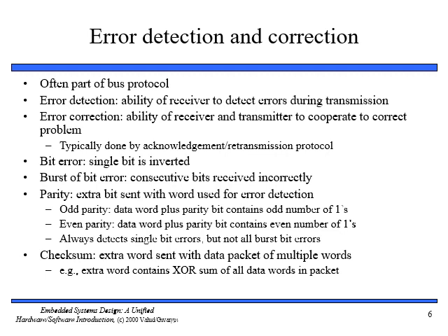On reception of the data word and parity bit, the receiver will compute the parity of the data and make sure that it agrees with the parity bit received from the transmitter. If a parity bit check fails, it indicates with certainty that there was at least one transmission error. Parity checks will always detect a single bit error. However, a burst bit error may or may not be detected by parity checking, an even number of errors, for example.